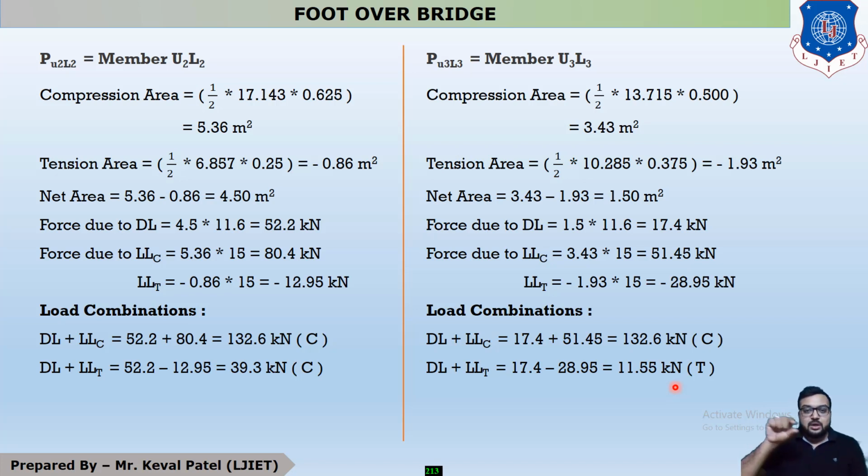Okay, so for a compression member we will design using Pd equals Ae into fcd, in which we have to find the effective area Ae, and as per the area requirement we have to provide more area than the required area, and we will check whether our selected section passes or not. Okay, so it is your homework from the last lecture that you have to design the vertical member.